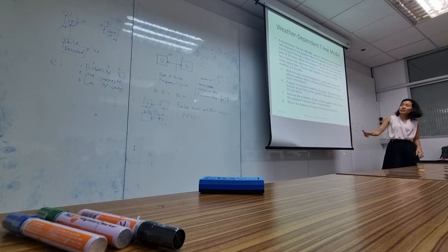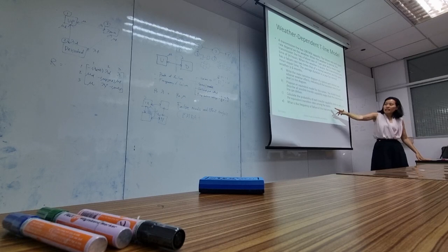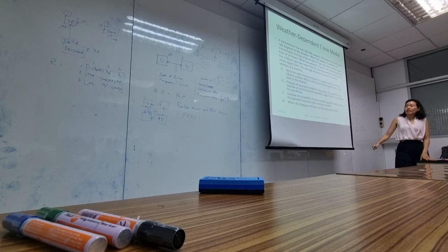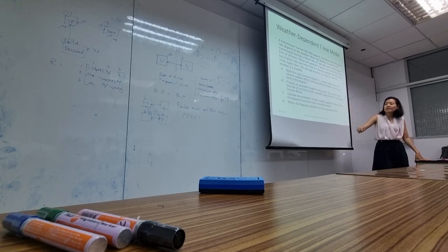But now, because it has weather, that gives a different failure rate. How can we combine these two to give an equivalent model? What does equivalent model mean? Equivalent model means that I can know the transmission line giving 0 at this probability, 100 megawatt at this probability, and the rates between them. Okay, and then you calculate the probability of each transfer capability state as well as equivalent transition rate, and then find the frequency of failure.